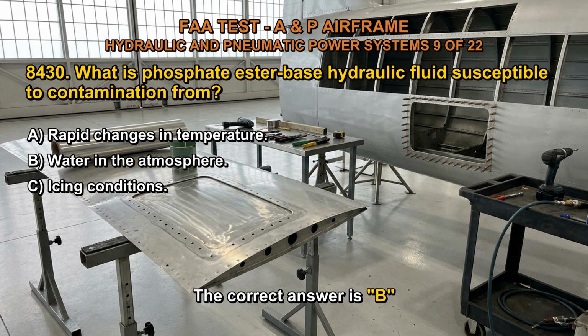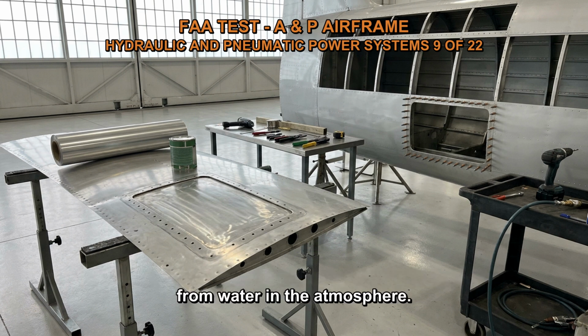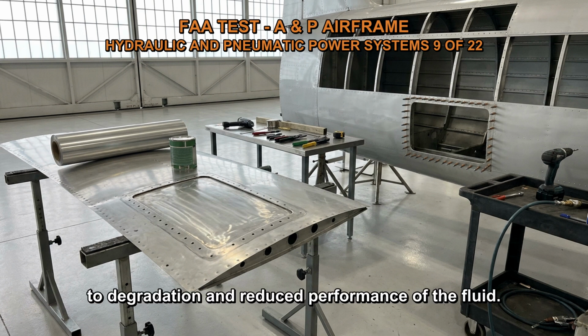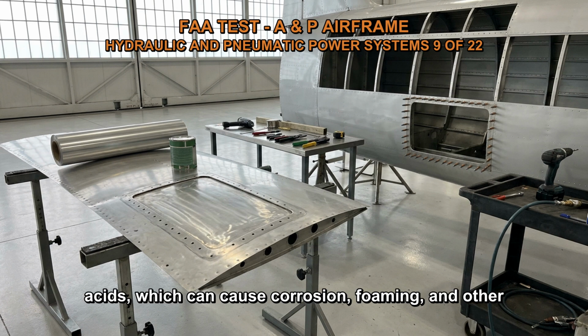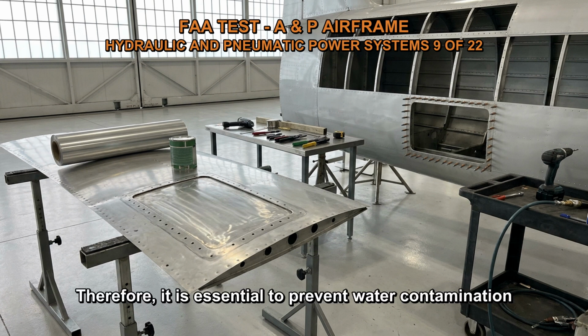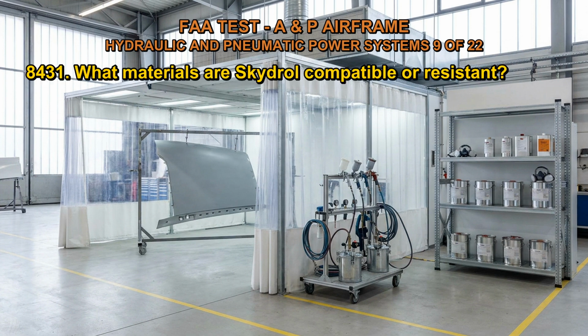The correct answer is B. Phosphate ester-based hydraulic fluid is susceptible to contamination from water in the atmosphere. Phosphate esters have a high affinity for water, and even small amounts of moisture can lead to degradation and reduced performance of the fluid. Water can react with phosphate esters to form acids, which can cause corrosion, foaming, and other issues in hydraulic systems. Therefore, it is essential to prevent water contamination in phosphate ester-based hydraulic systems.